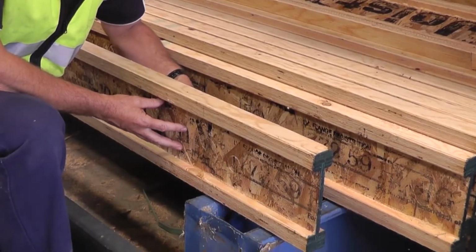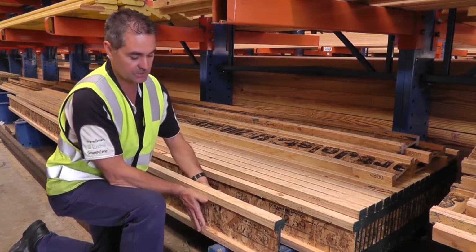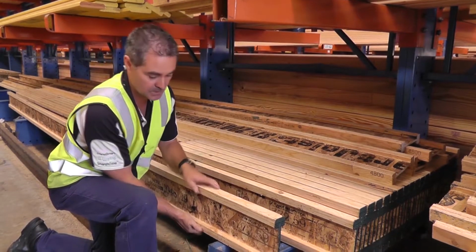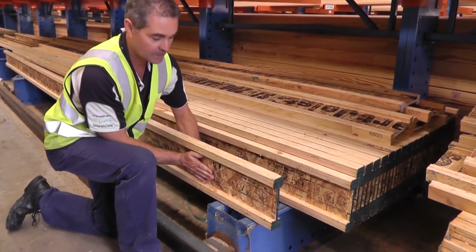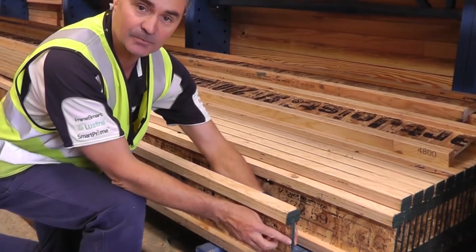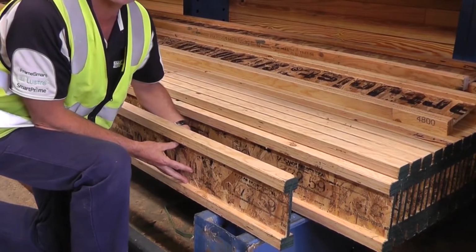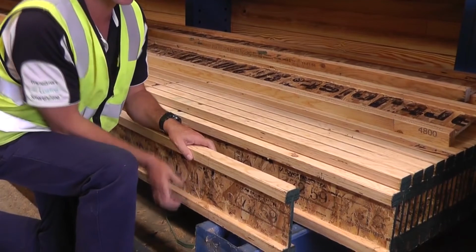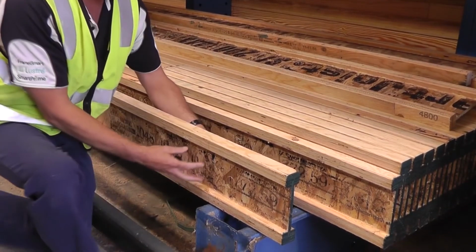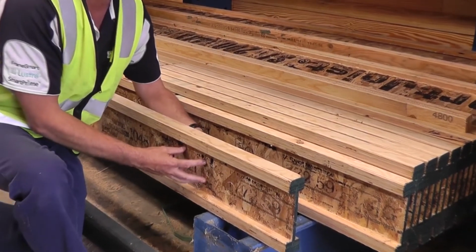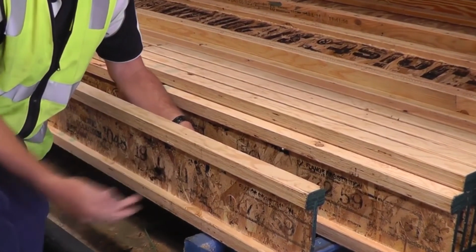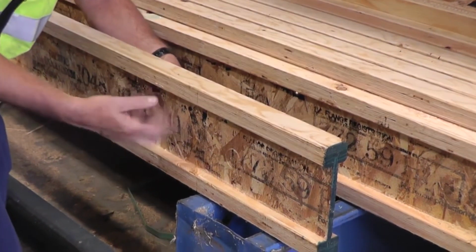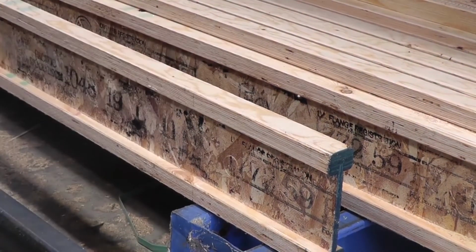This product is called an I-joist. The construction of this has a top and bottom flange made out of LVL, and it has a centre webbing. The centre webbing is about 9.5mm thick, and that's made of a product called OSB. OSB is oriented strand board. This is used very much in second story extensions, and a lot of the plumbing, air conditioning ducts, and any pipe work goes through the centre OSB webbing, and it is cut by holes.